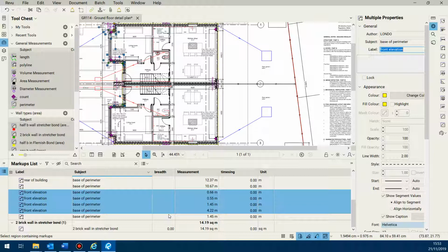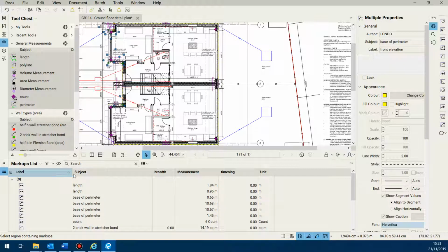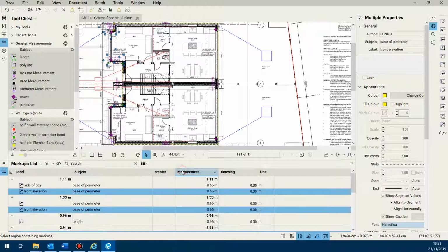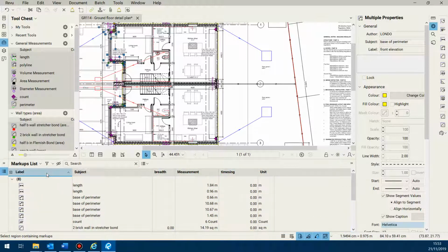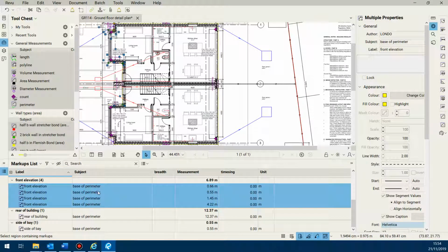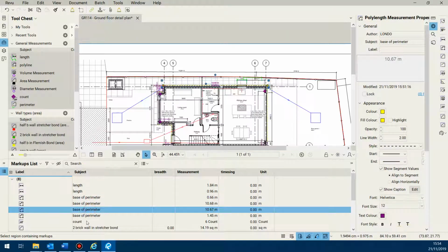And just on a final note on that, Bluebeam will export your data in a particular order. Just before you export, and we'll do this again when we actually do it, these column headings, if you click them, that is what it will filter this spreadsheet window by. So if you notice, I've gone and filtered by label. I've now got a random set of markups that don't really mean a great deal.